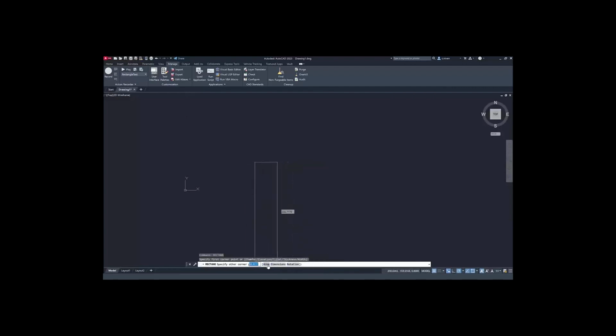So first corner point, and then we have a few new options here. So dimensions, that's where I'm getting that D command from. And so from here I can type in 100 and then 100. And then the only last thing really is picking what direction it's going in when we're using this method.